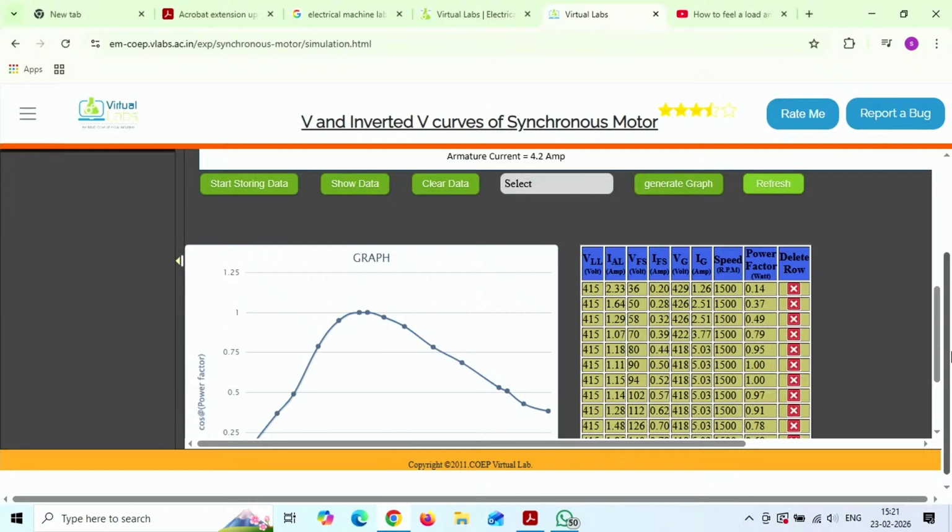Otherwise it is a very short interval of time. After that, if the fault is cleared, the synchronous reactance remains, right? It is mainly required. That experiment is also there for finding the reactance parameters of an alternator. Positive sequence, negative sequence and zero sequence. Positive sequence is what we got during the short circuit test and open circuit test.